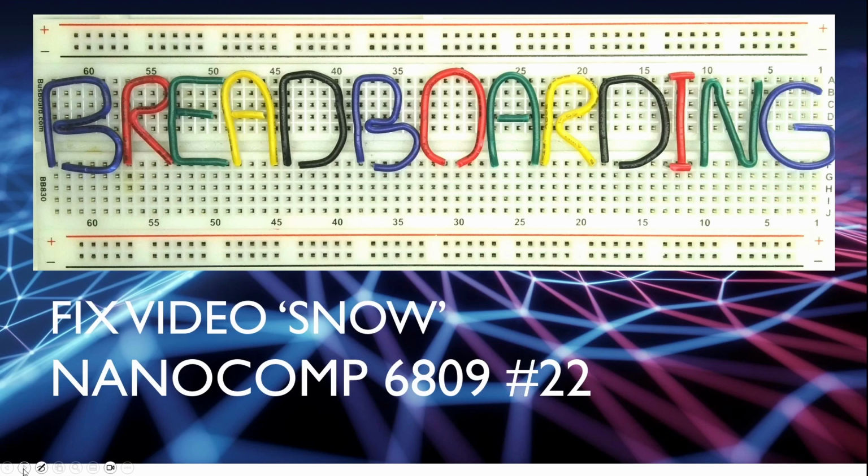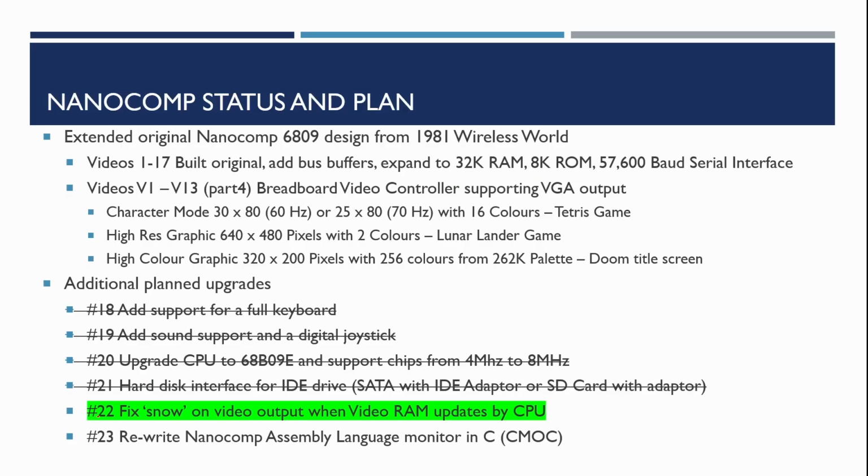Welcome to breadboarding. This is video 22 in the Nanocomp 6809 breadboard computer series. In this video, I'm going to be looking at fixing the snow on the video outputs, and this is caused by the CPU accessing the video RAM whilst it's being used for the display.